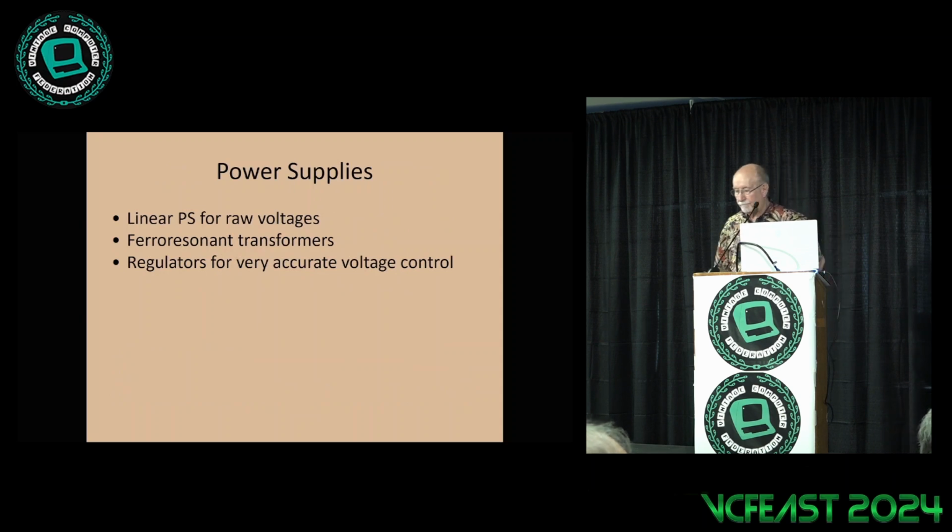So now power supplies. I mentioned there being lots of rails here. So we've seen with just this medium speed SLT logic that they use +6, +3, and -3. So that's 3 separate power supplies you've got to get working right just to power this particular type. IBM's power supplies were designed in the 1950s for their 1400 and 7000 series. And they didn't see any reason to change for the SLT generation through the 1960s.